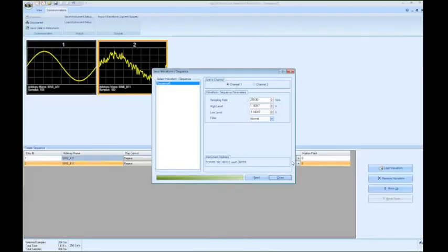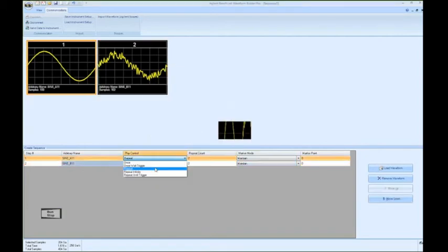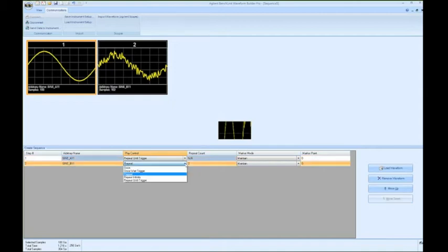Let's go ahead and take this yet another step and actually use some triggering with our signals. So I'm going to pop back over to Waveform Builder Pro, and I'm going to change the parameters just a little bit. First thing I'm going to do is repeat the clean sine wave until trigger, which means that this is just going to be a continuous sine wave until I have a trigger event. And then let's change it up from 2 to 3 so that when I do press that trigger button on the generator, I'll get 3 of these noisier sine waves.